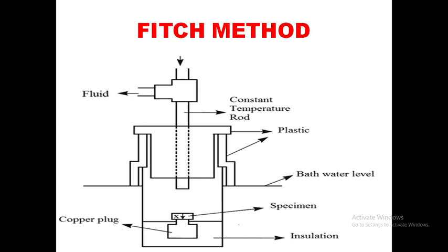The heat source is a vessel filled with a constant temperature liquid. The heat receiver is a sink in the form of a copper plug, insulated on all sides but the one facing the vessel. The roles of the heat source and the heat receiver can be changed if the vessel is at a temperature lower than that of the copper block. The specimen is interposed between the vessel and the open face of the plug.